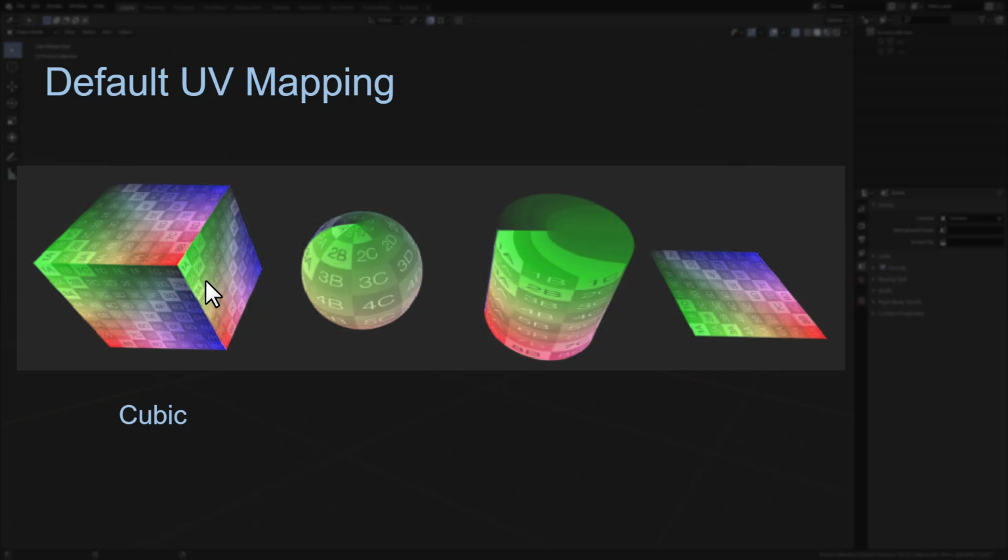Cubic projects the material onto the object from 3 points of view. Spherical attempts to wrap the material around the surface like a globe. Cylindrical wraps the surface with the material only in 2 directions, like the label on a bottle. And planar simply projects the material onto the surface from its normal direction.